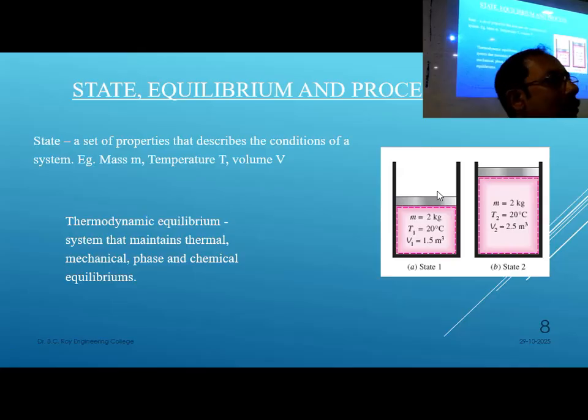When you are melting some solid, there can be some semi-solid condition that you cannot call a state, but it's a phase. Now, the same solid material can have multiple allotropes. Diamond, graphite, fullerene, these are all crystalline carbon. They are all solids, same state, but they all have different morphological properties. Allotropic behavior is different, so in that case, we say they are in different phases.